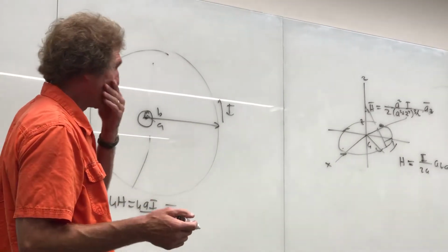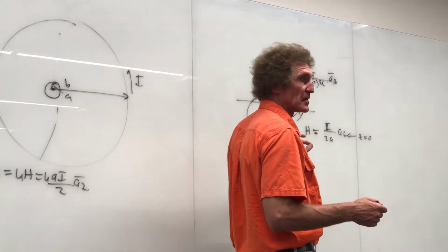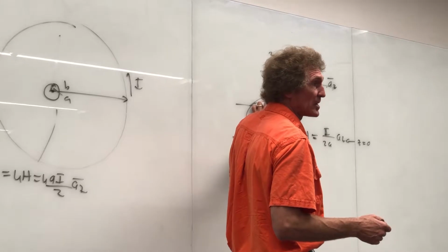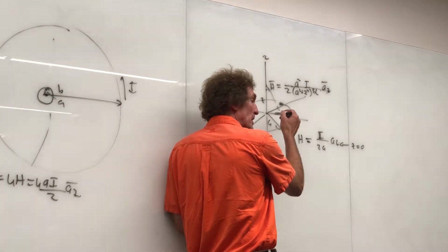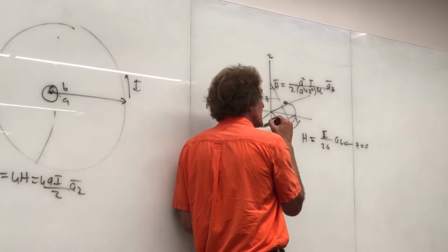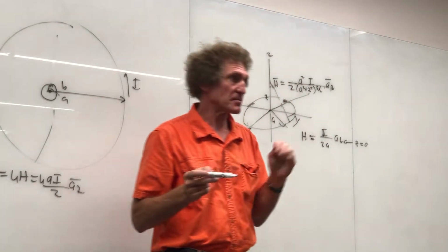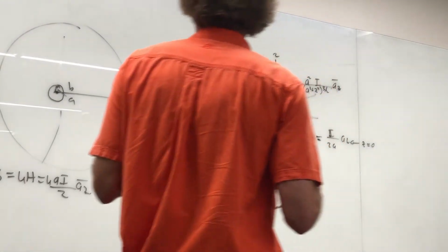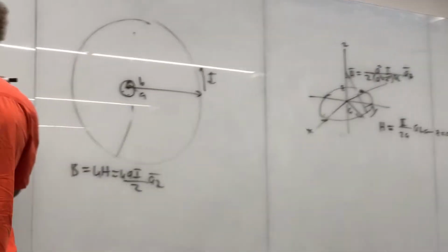You can actually prove that. This is only on the z-axis, but you could write the general formula for the H field at any point x, y, and z, then take the derivative with respect to x and look at how it varies, and a derivative with respect to y, and you'll see it varies a very, very small amount for small changes, like a over 10, from the center point. So therefore, we say that the B field is going to be about constant in there.